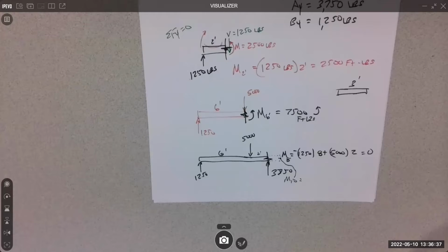Now we have shear. So shear is two forces, an up force and a down force, right? And it can be either this way or this way. Those are the only two combinations. If the left side is going up, this is how I remember it, it's positive. If the left side is going down, it's negative. So the beam force controls it for me. That's how I can remember this stuff.